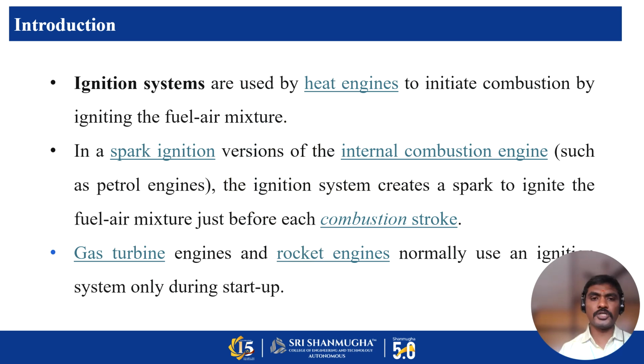Ignition systems are used in heat engines to initiate combustion by igniting the fuel air mixture. In a spark ignition version of the internal combustion engine, such as a petrol engine, the ignition system creates a spark to ignite the fuel air mixture just before each combustion stroke. Gas turbine engines and rocket engines normally use an ignition system only during startup. So this is the introduction of ignition system.